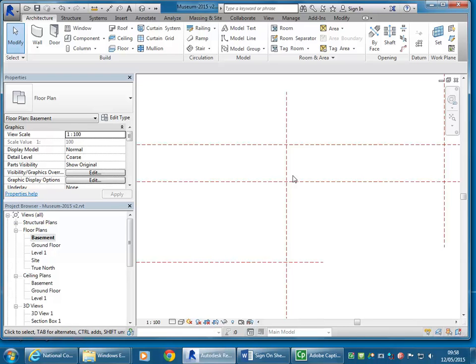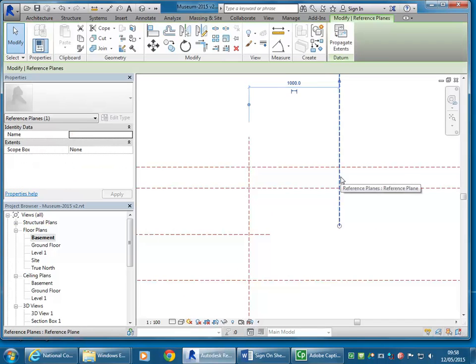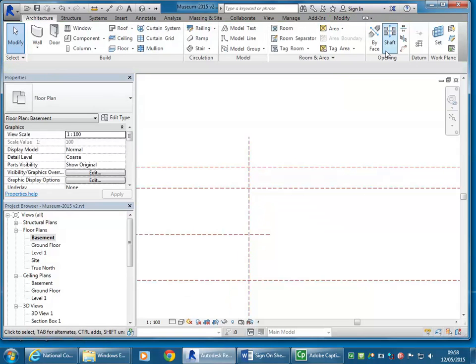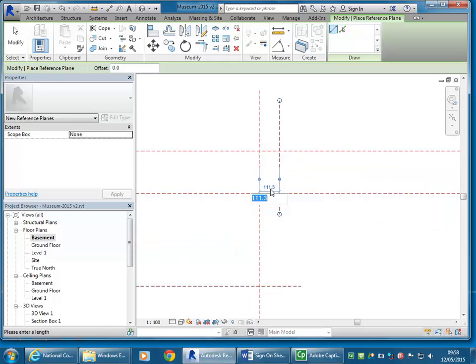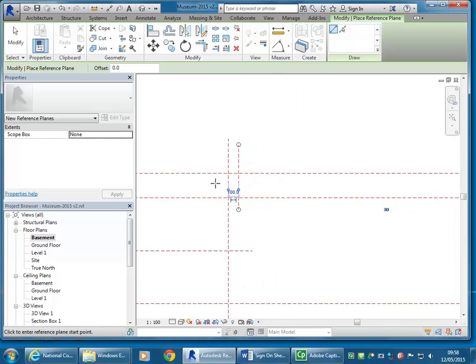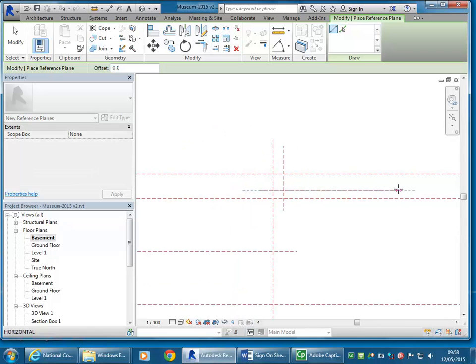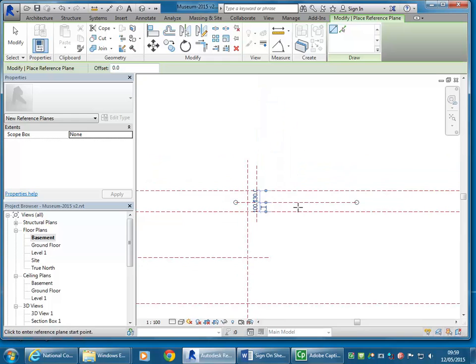And if you have a look at some real stairs, you'll notice that when they have that sort of transition, the railing suddenly goes up a big distance, and it looks a bit unusual, and it's just generally a bit awkward. So it's good to leave a gap there. So rather than doing it a metre from the end of this last riser, if you can add in some extra room there, even just 50 mil, but 100 mil would be good. And then the same going the other way. Okay, so coming across here, adding in another 100 mil. And then begin the next step there.